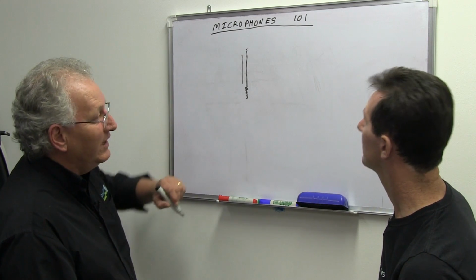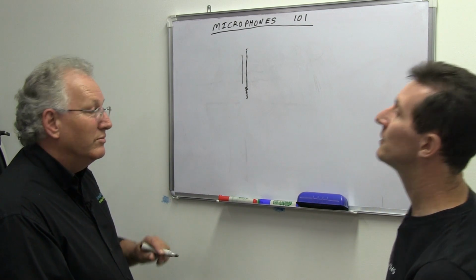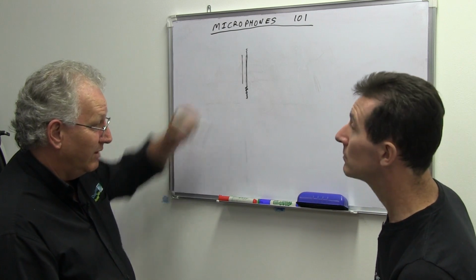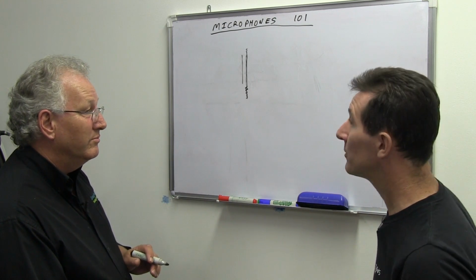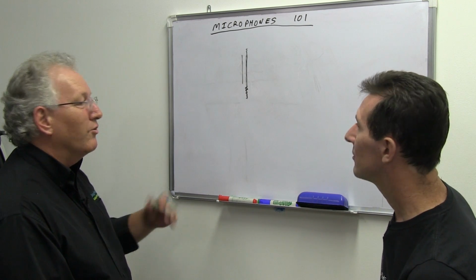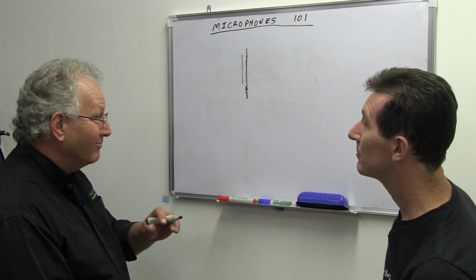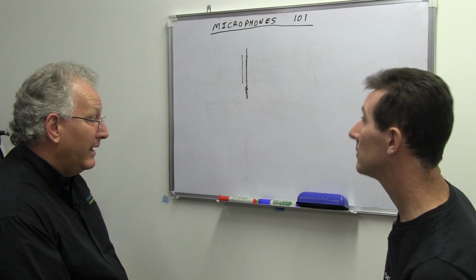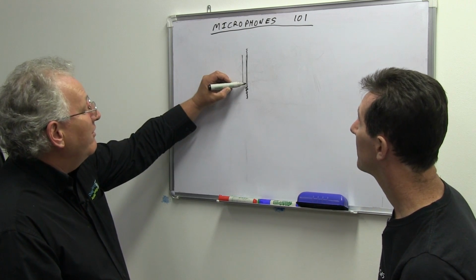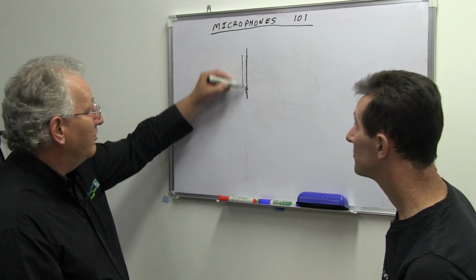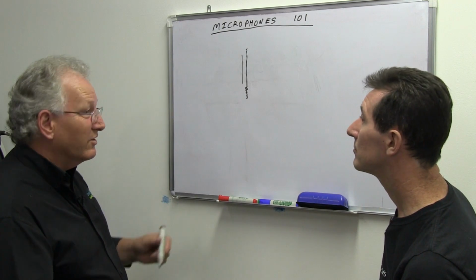Why does it need to be gold sputtered? Basically because you need a conductive surface. But it doesn't have to be gold. No. Gold just sounds fancy in marketing. It's marketing wank. And it doesn't rot off. Silver will. You know, silver corrodes. It tarnishes. And incidentally, very, very thin stainless steel is also used as the diaphragm. But mostly it's gold sputtered.